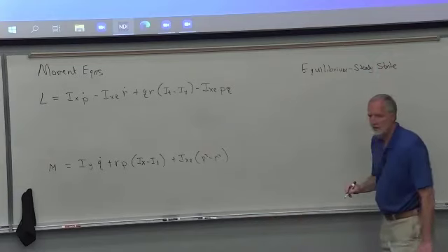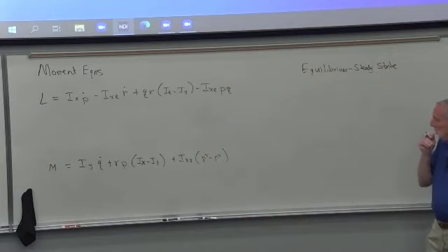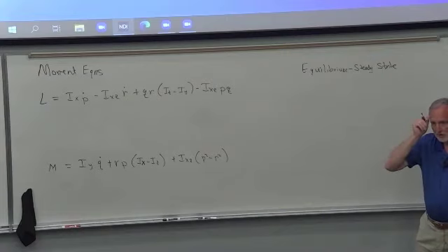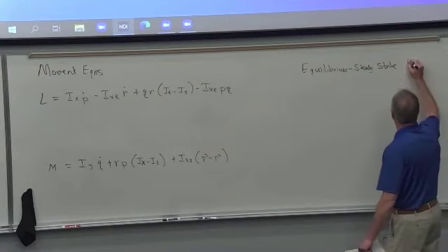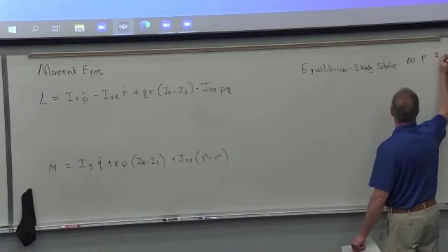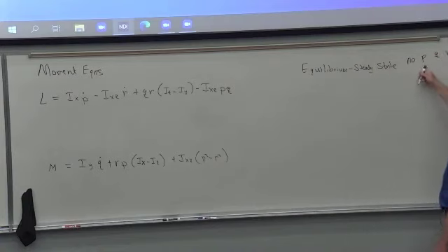And so we refer back to that steady state flight condition where we were only flying forward. We had a forward speed and that was it. And we had no P, Q, or R. That is no roll rate, pitch rate, or yaw rate, because we were saying we're flying straight and level. It's a cruise flight condition. If we were doing say a pull-up, then we would have a Q0 term in that, because that steady state pull-up would have a pitch rate, a constant pitch rate. But we're not doing that. For this, we're just doing the cruise flight condition.